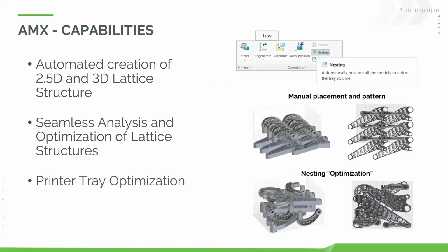Once you've got that, your design is done, you got to throw it on a printer tray. So you can lay out a single part, you can lay out nested parts, so basically just a print layout for multiple parts, and then figure out how everything's going to work. What's the optimal configuration? And once you find that, save this nest as a Creo assembly that you can manage and then easily modify just inside of the additive manufacturing extension.